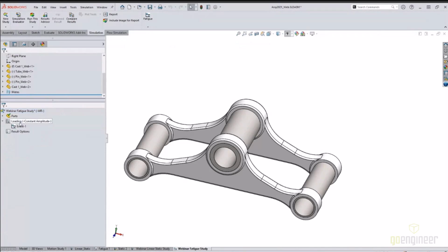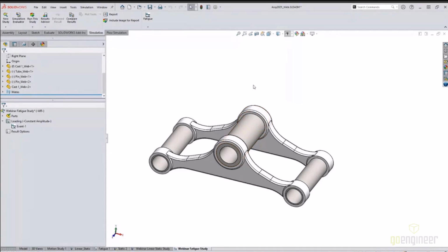We've already created our event. The event is the cycle load. And what type of loading? It's fully reversed, which means we're going to pull up here, go back down to the initial position where it started, and go down in that direction 5,000. So pull up 5,000, go back to initial, and go back down. All right, so that should be it in terms of setup. I'm going to go ahead and click save, and we're going to run this now.